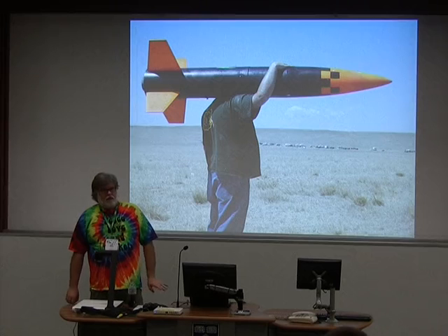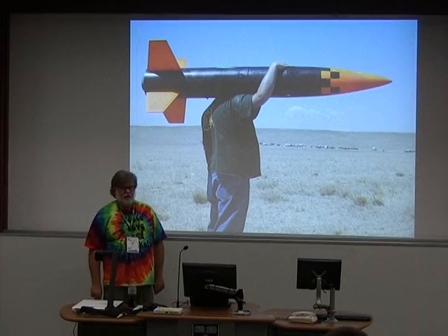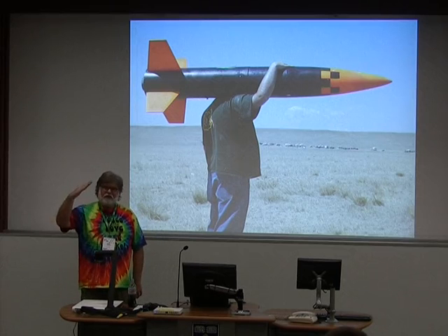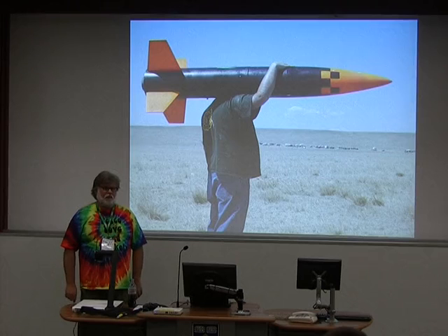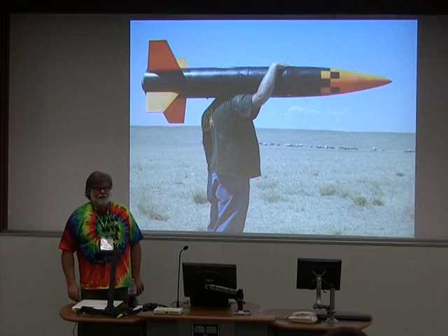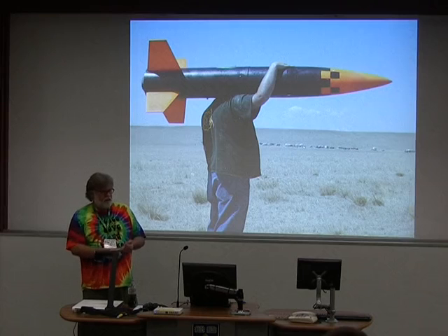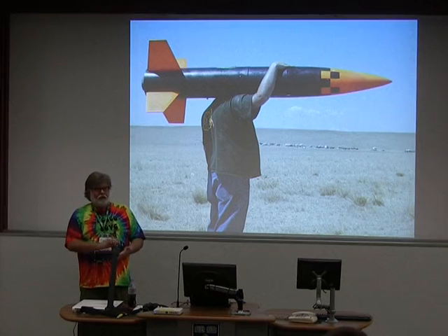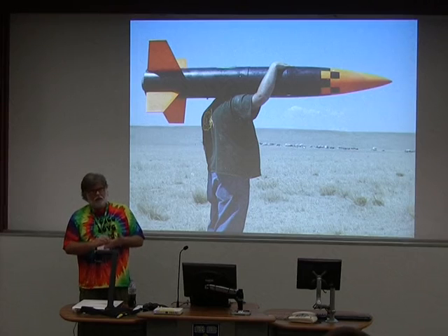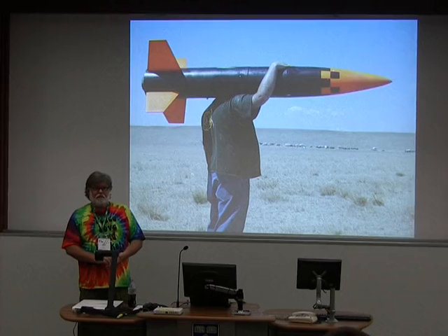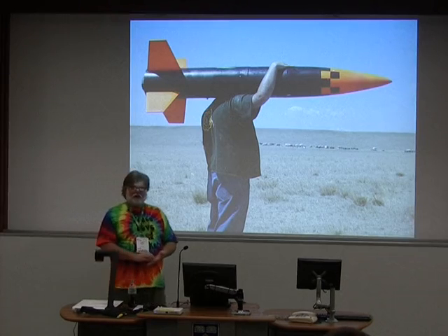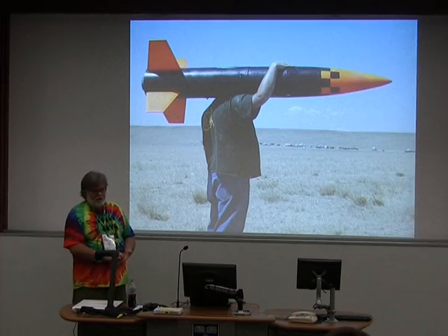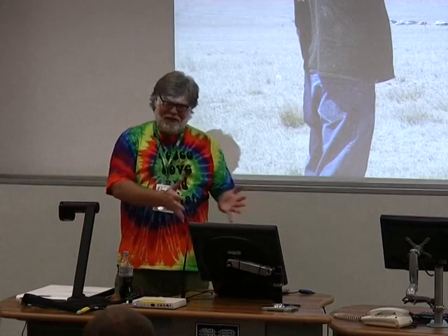And that's where a lot of the time gets spent, obsessing over the details of, we ought to pull those passives a little farther away from the mounting screw in the corner because somebody's going to whack them off the board using a screwdriver that's too big. That's happened. And it's stuff like that, so there's not a single place where I've actually ever copied a TI ChipCon artwork reference design. I always look at them. I always sort of lean back and stare at them, and I wonder what that intern was on when he designed that. And I mean, look, I worked at HP long enough. I know exactly where app notes and ref designs come from. They're the things you give interns to work on, and somebody provides advice and guidance. And in the end, they all get blessed before they get put out.